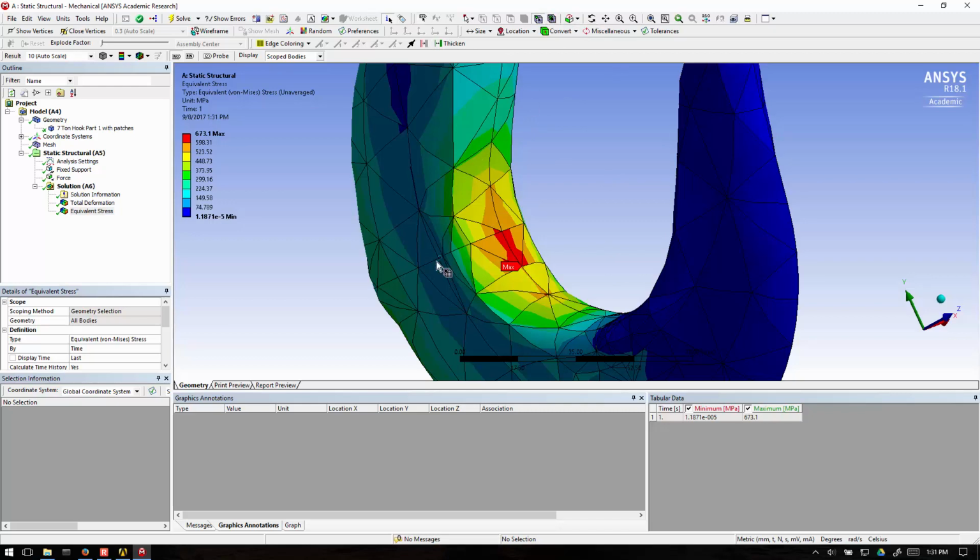Allow me to select nodes or elements. So I'm going to click two adjacent nodes. And again, to click two nodes, you have to hold Control. Now down here, it's showing me a window that shows the distance between those. Right now my element size is about 16 millimeters.